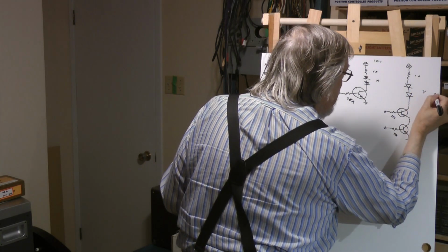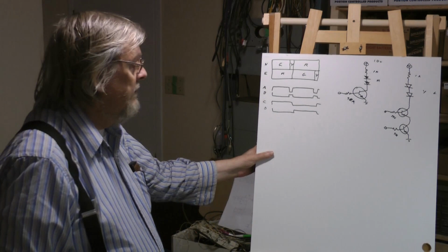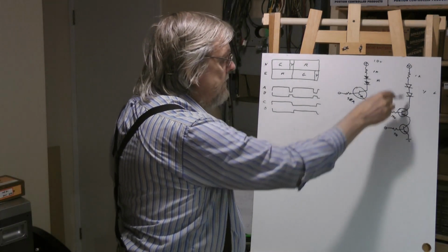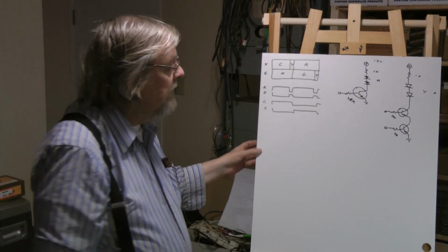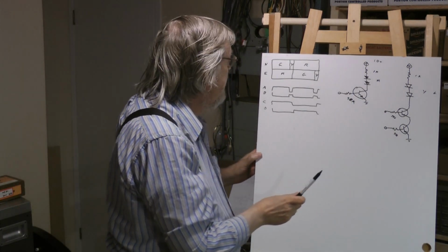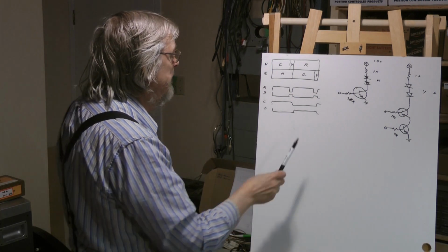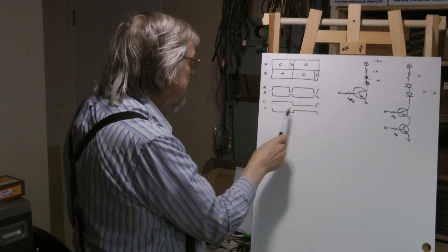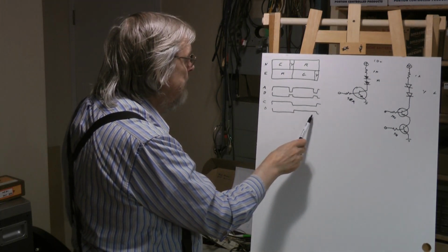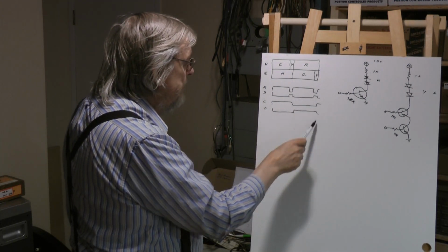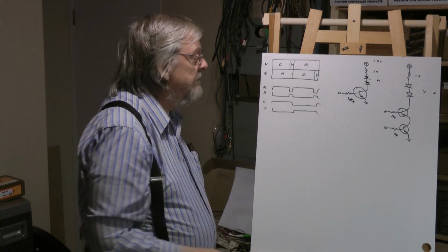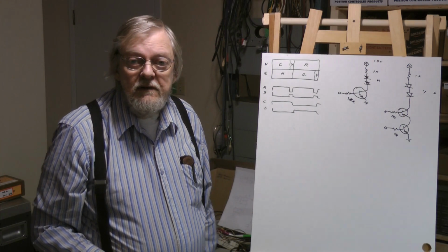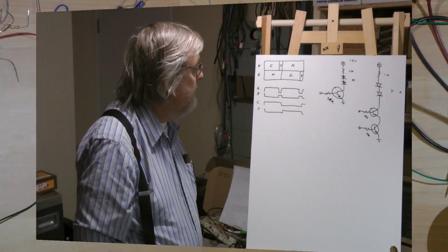These would be either the yellows or the greens. Now, turning one of these transistors on is not going to give you any current. You need to turn them both on. That's why that's an AND gate. So for example, green east, you would want signal A and signal D. You would only get the green east during that time. Well, let's go look at the breadboard and see if it works.